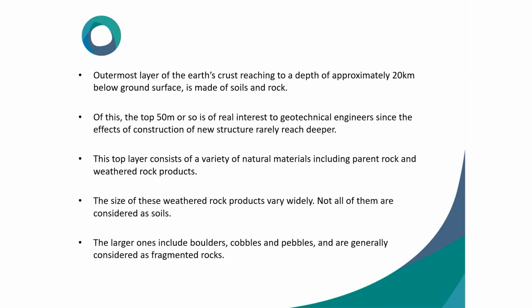The outermost layer of the earth's crust, reaching a depth of approximately 20 kilometers below the ground surface, is made of soil and rock. Of this, the top 50 meters or so is of real interest to the geotechnical engineer, since the effect of construction of new structures rarely reaches deeper. That's why you get the difference between shallow foundation and deep foundation. When you want to go shallow and when you want to go deep, this is the beauty